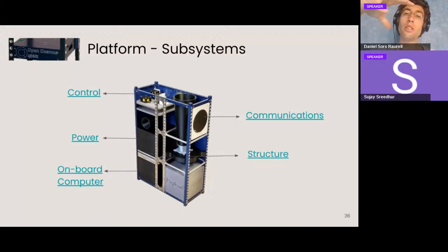For our mission, that would be important because if we want to have the right levels of microgravity, we don't want our satellite to spin around because that can generate accelerations. So we want to make sure that the satellite is stable and the microgravity levels are exactly as we want them to be. There is a power control unit, what we call normally the EPS, so we regulate the power, the voltage, the intensity, so the payload and all the instruments are well supplied, and we obtain all this power with solar cells normally. So we obtain this solar energy from the sun, we store it in batteries, so when we are in eclipse or when we need extra power, we can use it. So that's a very important system as well.